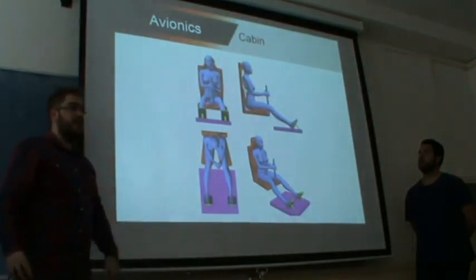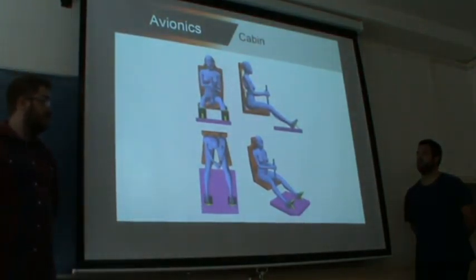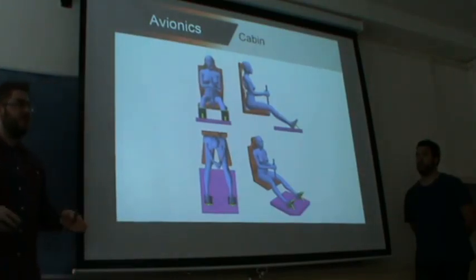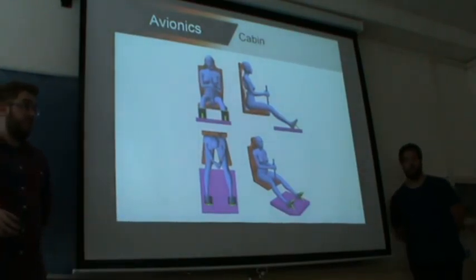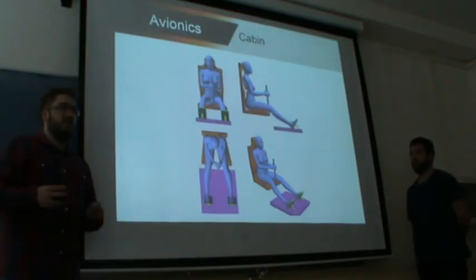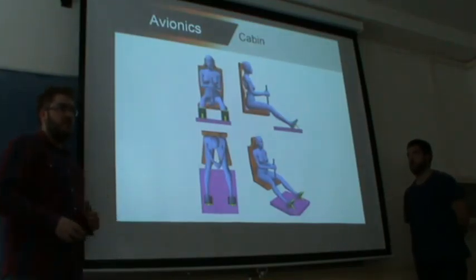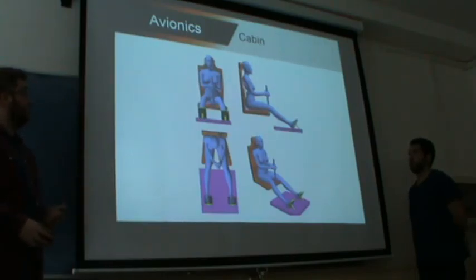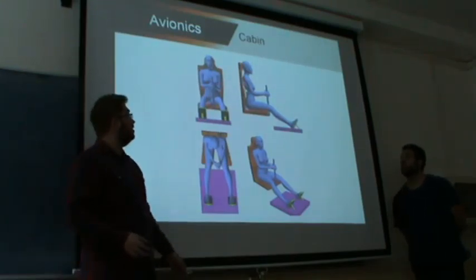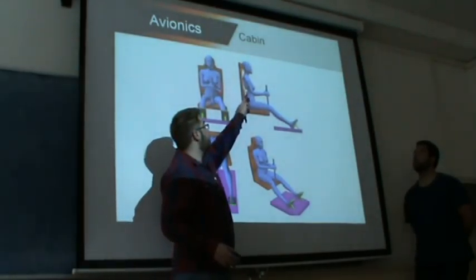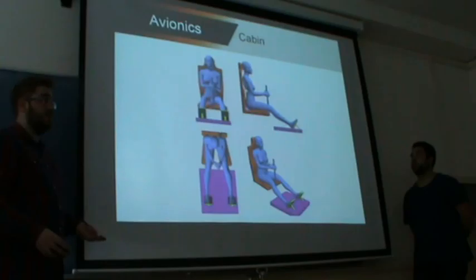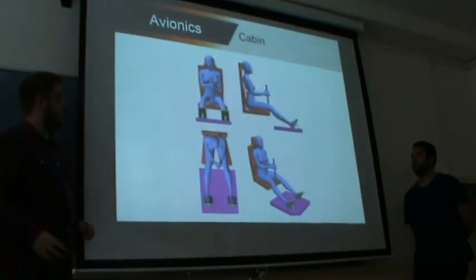We have given some extra space for the parachute of the pilot, because most of the competitions require the pilot to have a parachute in the airbag. For example, if they have to do some kind of evacuation or something like that, they have to wear the parachute. So we cannot make a contact between the back of the pilot and the back support of the seat, because it would cause the pilot to be a little more displaced to the front.